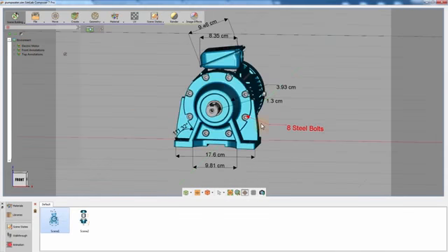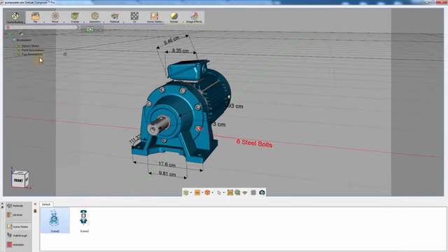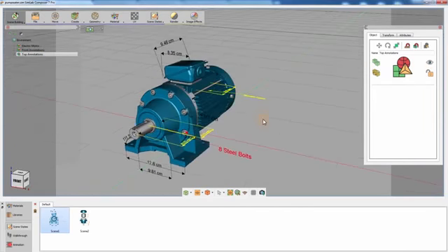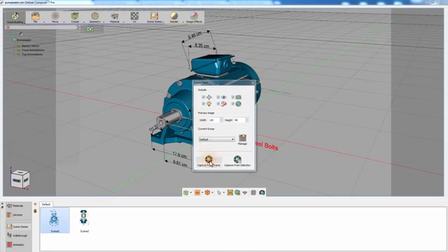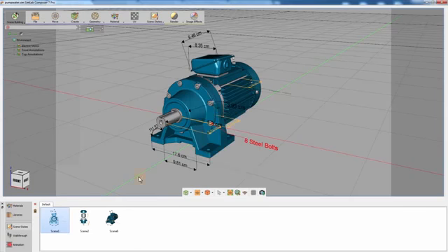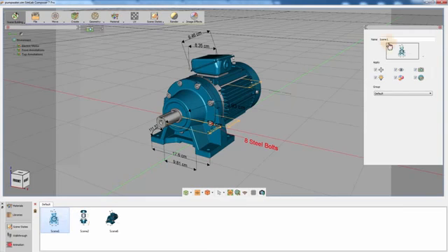Reveal all the objects and annotations in the scene. Set the camera to a perspective view and click Capture from Scene to create a third scene state. Click on the first scene state and from the Attributes panel to the right, rename it to Front. Select the second scene state and name it Top. And name the third scene state Perspective.